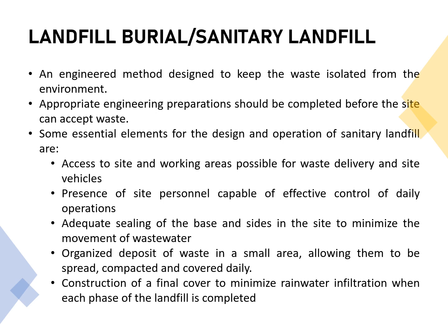So remember that the transport vehicles collect waste from the different facilities. So once they get into the sanitary landfill, there must be a specific area for them where they can pass through and dump their collected waste. Presence of site personnel capable of effective control of daily operations. So there should be someone who should oversee all of the activities that are happening in the sanitary landfill.